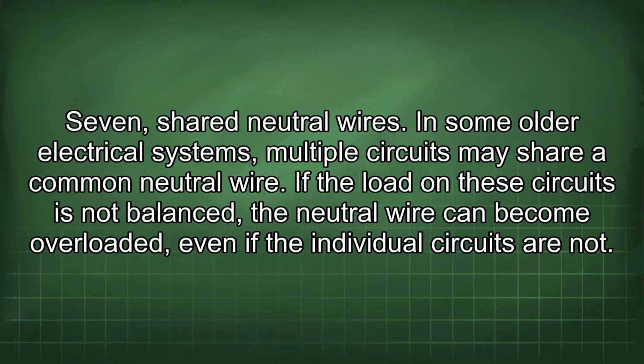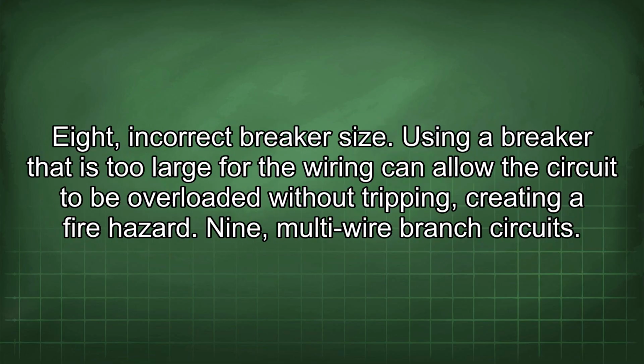7. Shared neutral wires. In some older electrical systems, multiple circuits may share a common neutral wire. If the load on these circuits is not balanced, the neutral wire can become overloaded, even if the individual circuits are not. 8. Incorrect breaker size. Using a breaker that is too large for the wiring can allow the circuit to be overloaded without tripping, creating a fire hazard.